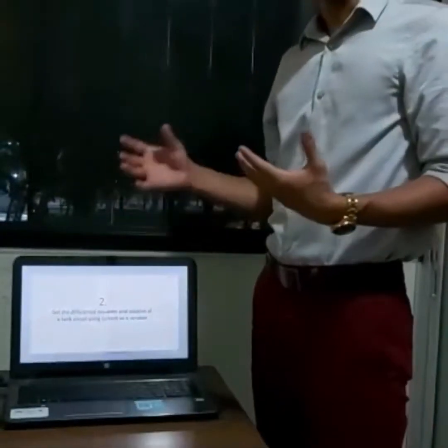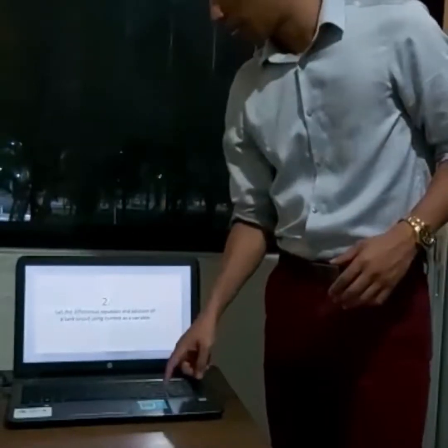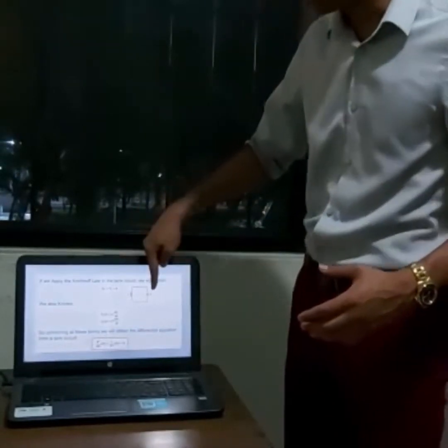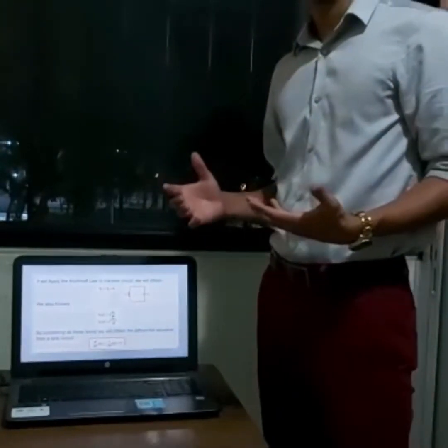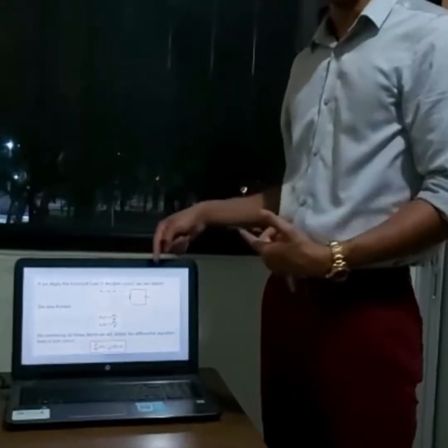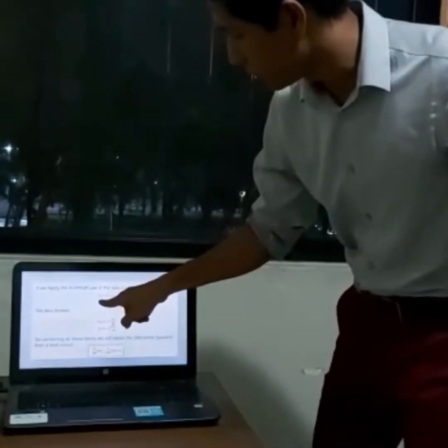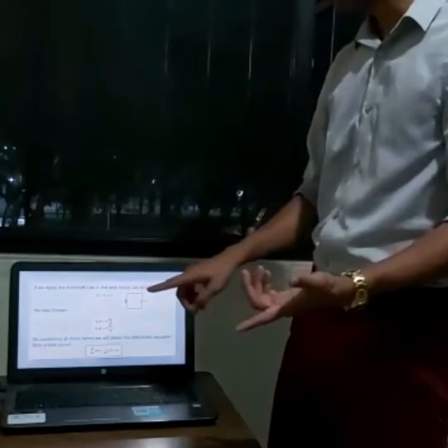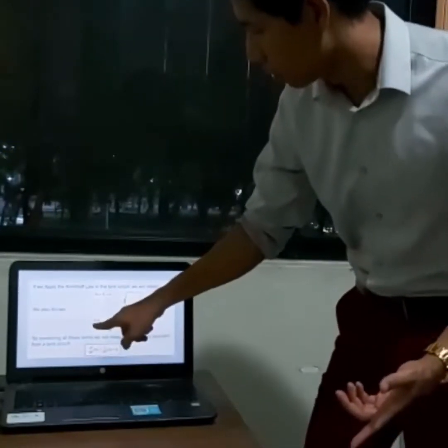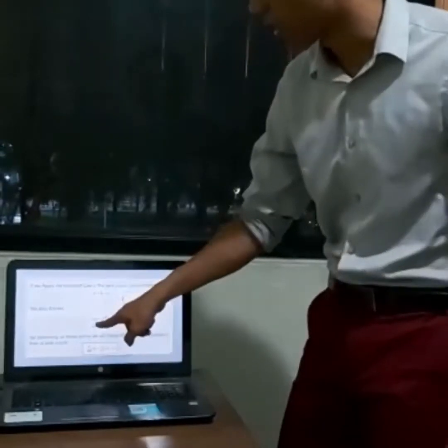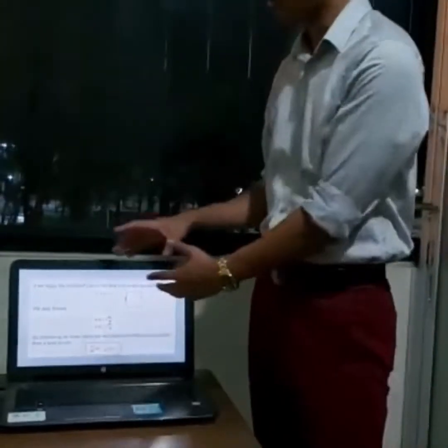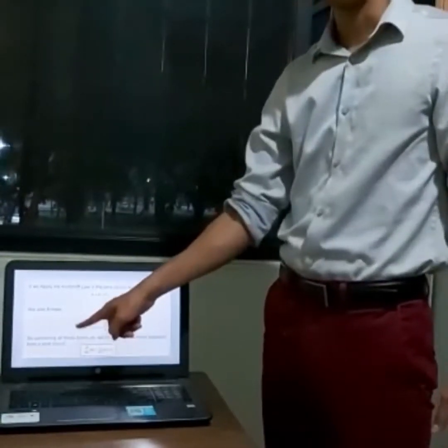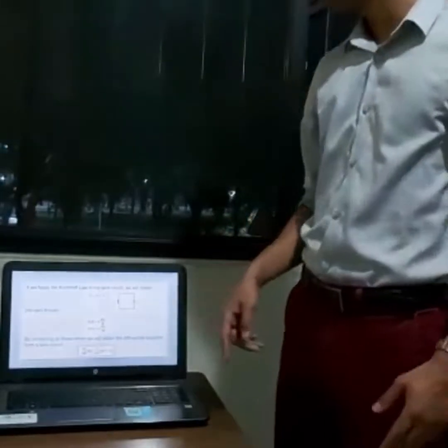We're going to get an equation for our tank circuit. As we can see here, we have the inductor and the capacitor in parallel. As we know, we can apply Kirchhoff's law here. So we have this equation, V sub C minus V sub L equals 0. We also know the voltage in the inductor and the current in the capacitor. If we combine these equations, we can obtain the second order differential equation for the tank circuit. Now we're going to solve it.